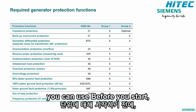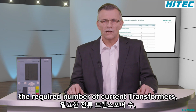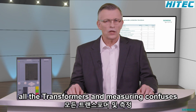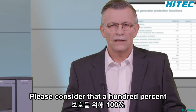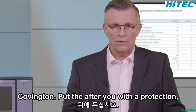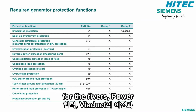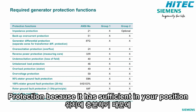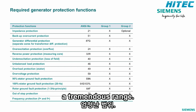You can use the SIPROTEC 5 configurator to select the device version. Before you start, make sure you know the required number of current transformers, voltage transformers and measuring transducers and the necessary number of binary inputs and outputs. Please consider that the 100% stator ground fault protection requires a sensitive current input. We have to use a protection current input on the protection device side for the reverse power protection because it has sufficient angle precision and the advantage of a wider current measurement range.